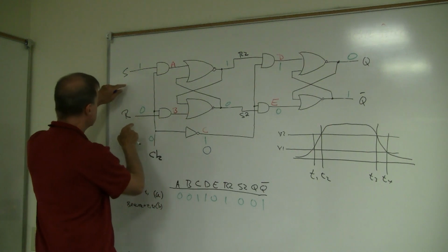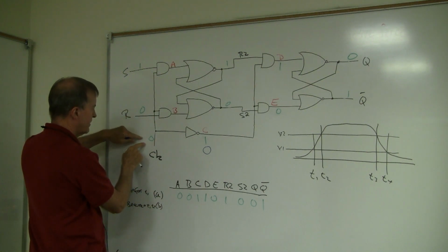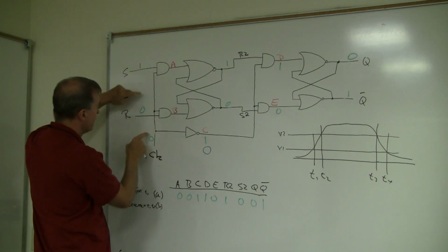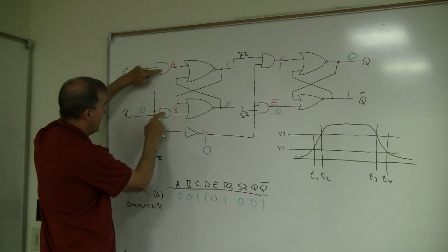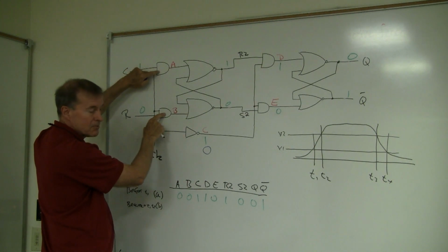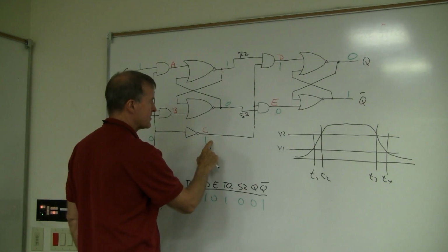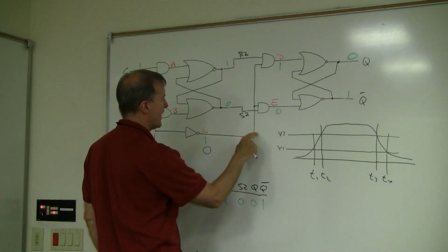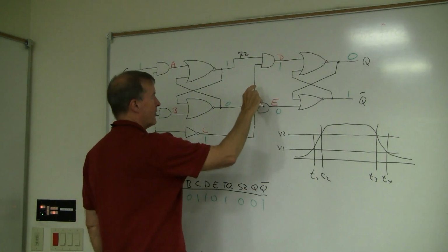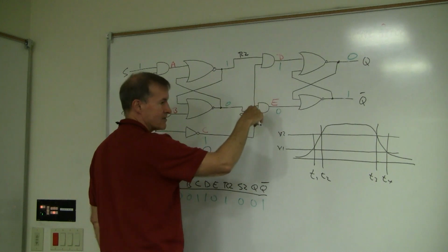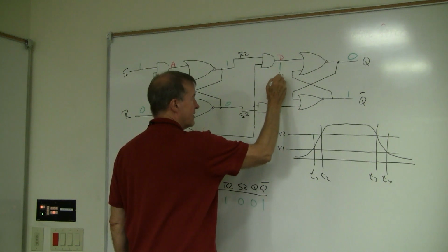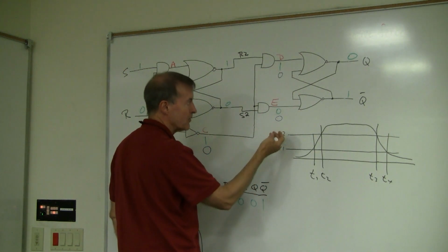Now these AND gates, the 0 from the clock hasn't hit this threshold. Are you with me? So these AND gates still have these zeros coming into them, right? But what happens when this flips to 0? Now this 0 is going into these AND gates. So what happens to signal D and E? They both become 0. E was already 0, but this one stays 0.